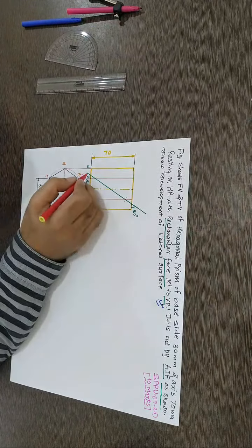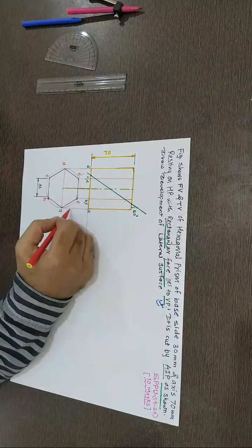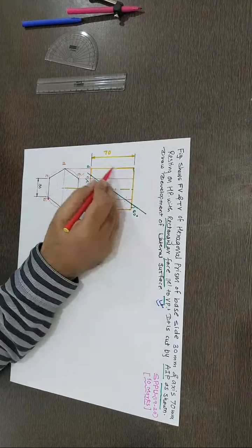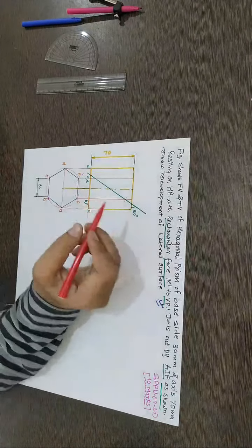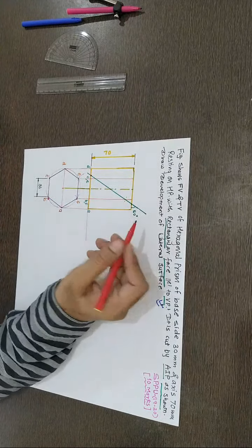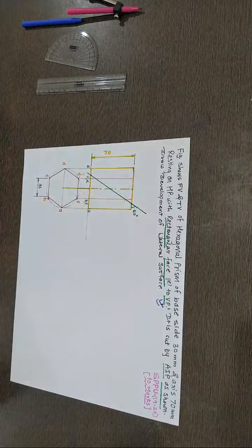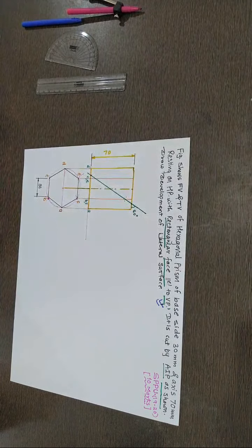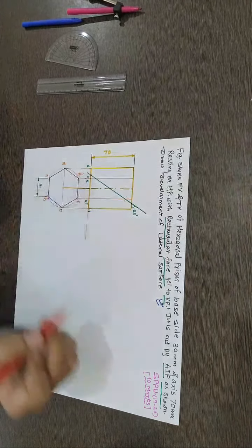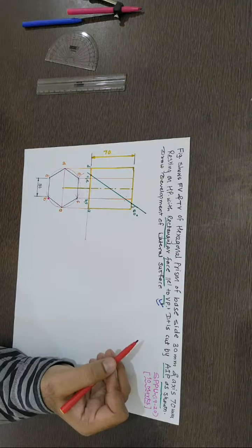So this intersection point and this intersection point are additional, and it is not cutting the two edges, as you can see here, this A edge of the prism as well as this D edge of the prism. I'm just using a convenient way to explain this. Actually, the edge should have another notation. If you want, you can give this A dash, this D dash, no problem. So for this edge and this edge, the plane does not have any intersection. So we are now interested in how the intersection of the plane with the top and bottom face of the solid, or we say the base, will look in the development.